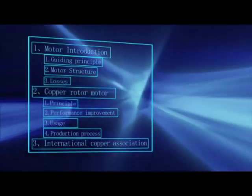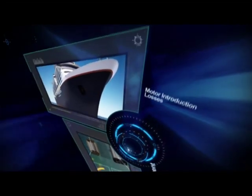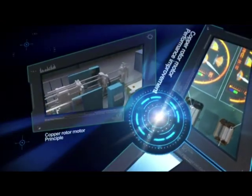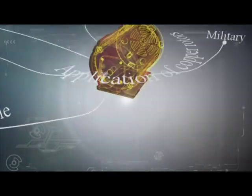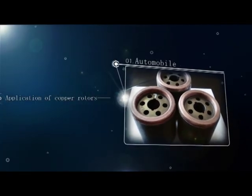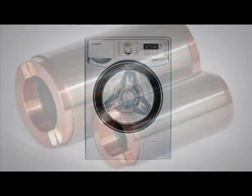Usage. These advantages make cast copper rotor motors suitable for small squirrel cage induction motors to replace the existing aluminum rotors so as to improve energy efficiency. Within the range of power, the use of cast copper rotors is the simplest, most effective, and economically feasible manner to produce high efficiency and premium efficiency motors.